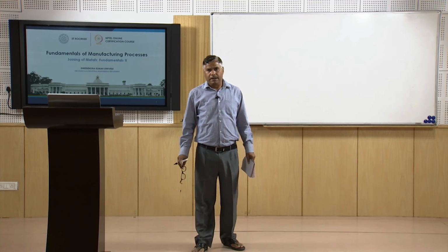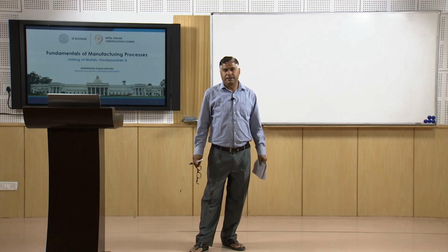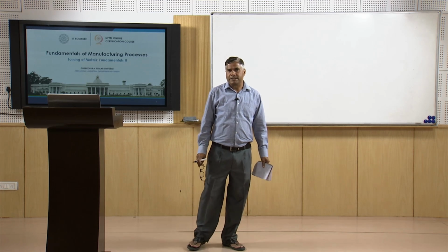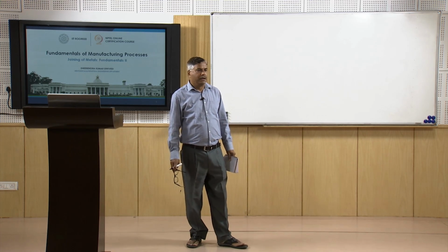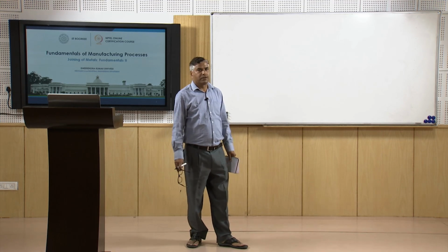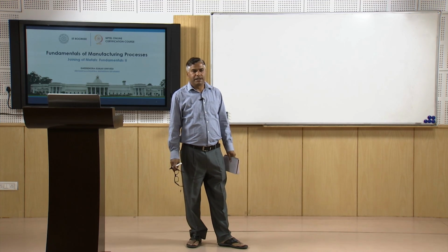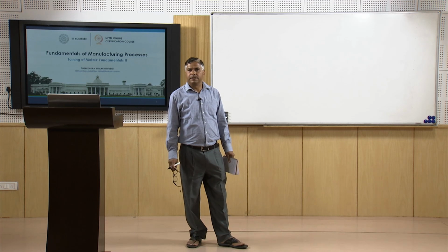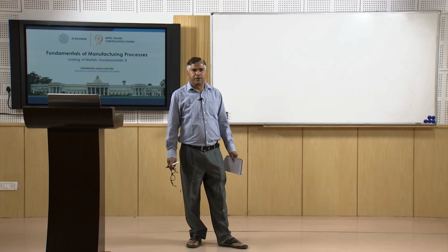In this presentation, I have talked about some of the basic aspects related to welding positions, the role of heat input in the development of sound joints, and how the power density affects the amount of heat required for welding. At the same time, I have also talked about how the energy density varies in the heat source, which is maximum at the center and keeps on decreasing as we move from the center toward the surface of the heat source.